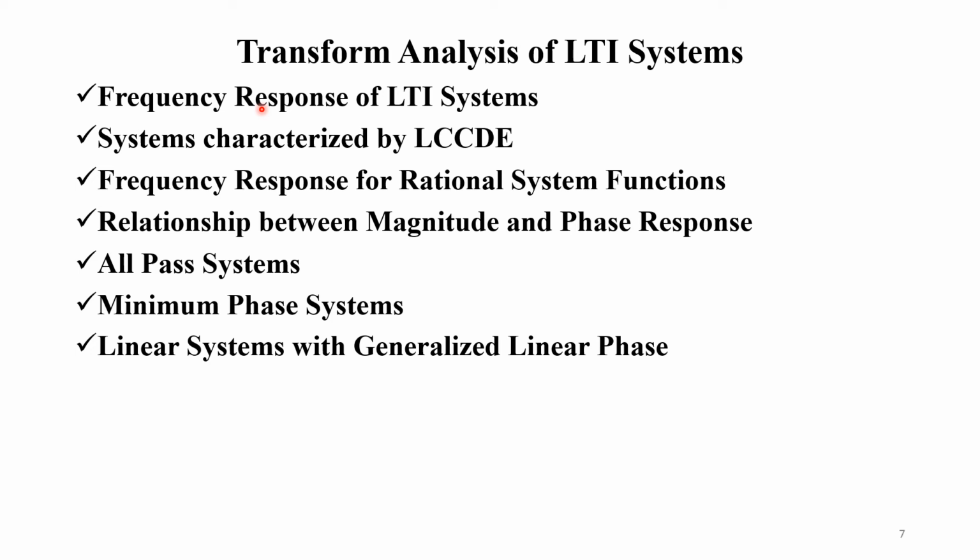The systems are characterized by linear constant coefficient difference equations. You understand there are different representations of the LTI system. One of them is the linear constant coefficient difference equation, and discrete time filters are the most typical implementation of the linear constant coefficient difference equation.